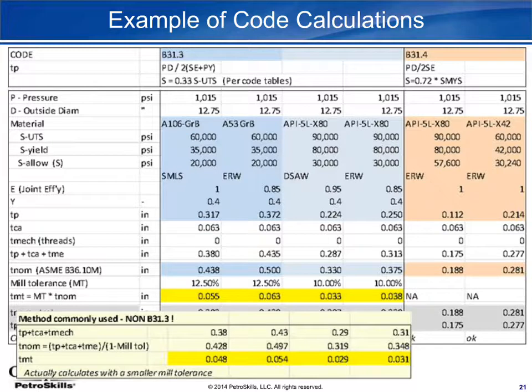But in B31.3, we assume that means go off and do a formal piping stress analysis using something like Caesar and so forth. The trick is working out when you need to do that and when you do not need to do that. Often, many companies have internal guidelines that will drive you towards this is when you need to do a stress analysis, this is not.